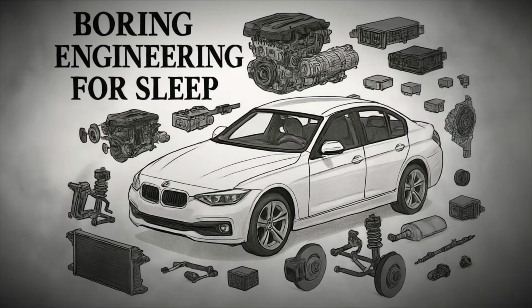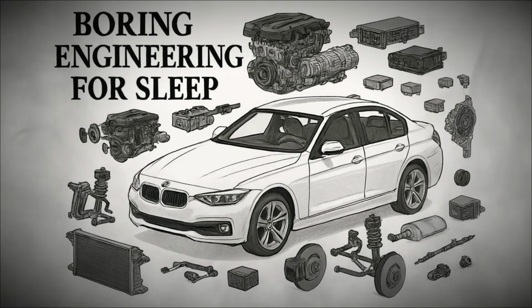A lower gear means the engine turns many times while the wheels turn slowly, providing torque for acceleration. A higher gear means the wheels turn faster for each rotation of the engine, making it efficient for steady, high-speed driving. Within the gearbox, there are components such as the input shaft, the output shaft, and the counter shaft, each carrying gears that mesh together. Synchronizers are used to match the speed of gears before they are engaged, ensuring smooth shifting without grinding.